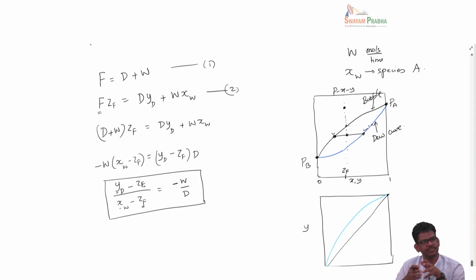If you continue to decrease the pressure even beyond, you may reach a point here where you would have completely vaporized all the liquid. The dew point line corresponds to entire vapor and one dew drop having a composition corresponding to this point. And if you decrease the pressure further down, you enter into a completely vapor phase. This has to be clear to you. In a TXY or PXY diagram, where to mark the single phase, vapor phase or liquid phase, and then how to draw the process when we heat it or when we change the pressure or the temperature.